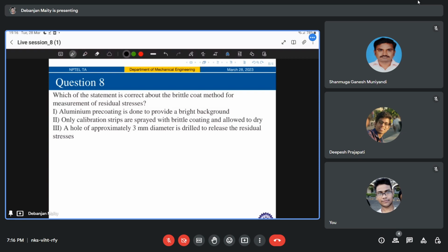Neither an analytical nor a numerical model-based simulation can be believed without experimental verification. So measuring this residual stress, including its magnitude and sign, is it tensile or compressive, as a function of location, possibly in three directions, is far from trivial in reality.